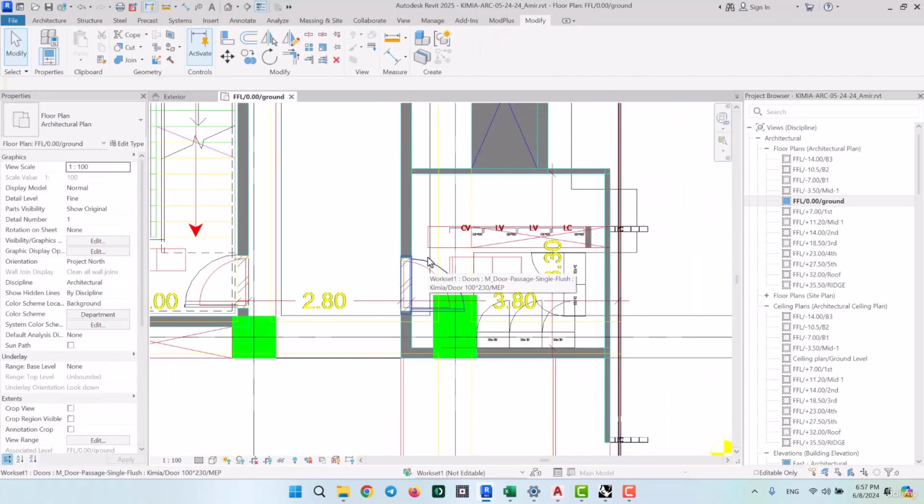So you're gonna have to also report these clashes. For example, for the parts where the opening is not fitting, or the architectural and structural don't match, all of those need to be reported. So for example, for this part, we might need to move the door and bring it higher. So this way you could just catch the clashes, and therefore one of the pros of modeling all of the disciplines in one file is that you can catch them. Okay, so let's draw this area.